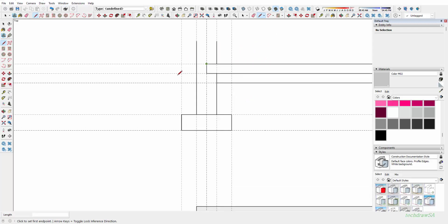So now with that done, we also know that your natural ground level, the NGL, is going to go here, which is always in line with the bottom of your hardcore, and you will then have the 45-degree ziggy-zaggy lines of your hardcore hatching here, going 45-degree up and down all the way through. Obviously you only have to do about a third of that hatching going to the right of your hardcore, and then you will also hatch your concrete surface bed with the appropriate hatching.